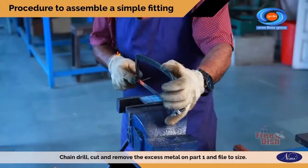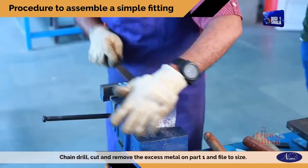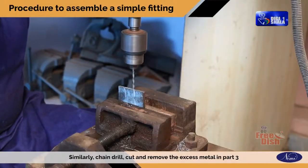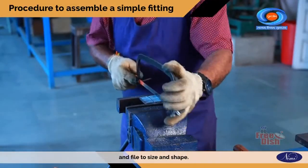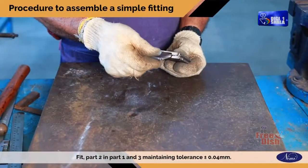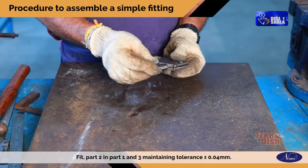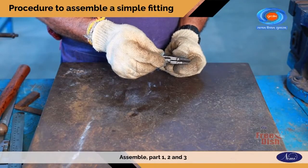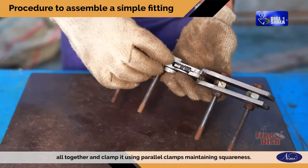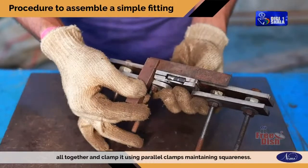Chain drill, cut and remove the excess metal on part 1 and file to size. Similarly, chain drill, cut and remove the excess metal in part 3 and file to size and shape. Fit part 2 in parts 1 and 3, maintaining tolerance plus or minus 0.04 mm. Assemble parts 1, 2 and 3 all together and clamp them using parallel clamps maintaining squareness.